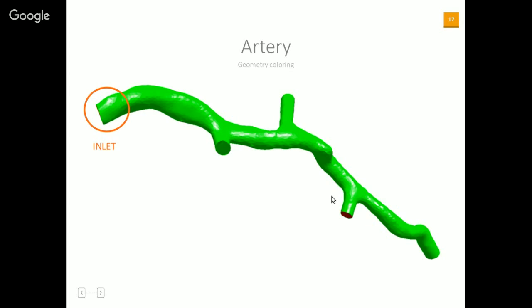So the file we are going to use is a STEP file, that is the best one because of its flexibility. First thing to do with your CAD, you have to colorate it. In fact, the AP214 allows you to assign colors to your surfaces. And it is very useful to define boundary conditions as well as surfaces.